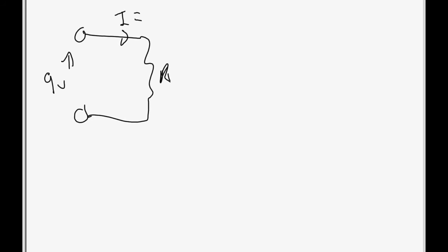Let's say we need 3 amps flowing in our circuit. How much resistance should the circuit have for us to get 3 amps? Resistance is what we want to find out. We definitely want 3 amps to flow in the circuit, and we've definitely got 9 volts, so it'll be 9 volts divided by 3. It's really simple: you need a resistor of 3 ohms.